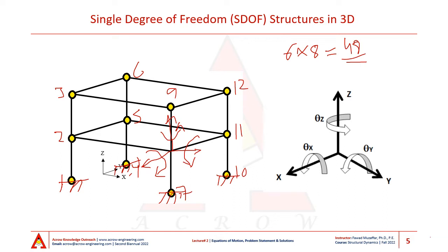Now, we do typically make assumptions when we are analyzing three-dimensional frames. The assumption again is that the horizontal frame elements, which are beams and slabs now, are not extensible. They are axially rigid and in plane rigid. This reduces the number of degrees of freedom by more than half, and we analyze the simplified structure.